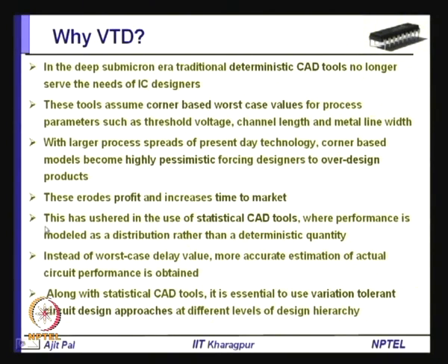So, in the deep submicron era, traditional deterministic CAD tools no longer serve the needs of IC designers. Nowadays, the CAD tools that you are using are based on a deterministic approach. By that I mean, they assume that the channel length, the threshold voltage and all other physical parameters are fixed. That means, for a particular technology, you assume a fixed threshold voltage, a fixed channel length, a fixed silicon dioxide thickness and so on, and based on that you do the design using different CAD tools.